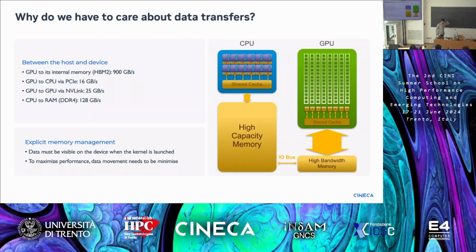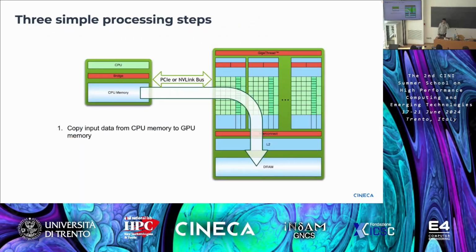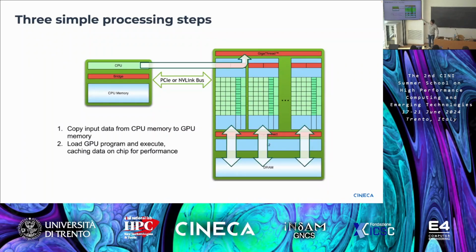What you get, well, the number I wrote because I just copied it from some presentation, was 16 gigabytes per second. Theoretically you get lower; in some cases you get 5 gigabytes per second. This is where you transfer the data, right? It has limitations. If you try to busy the traffic, for example sending data or receiving data, this can be costly. So the step that you want to follow is like this: you launch a kernel, you move the data, they execute, and they come back.